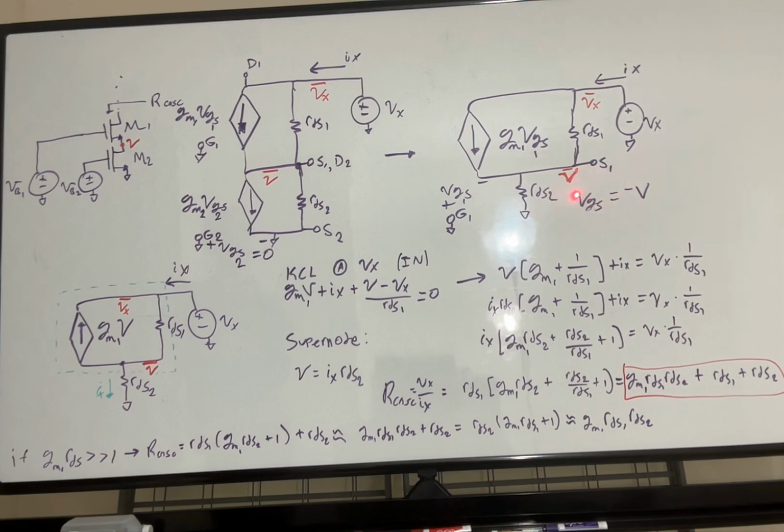So when I see that my VGS becomes negative, what I like to do is I like to redraw it but change the direction of the arrow. So now we've got a third circuit here. And all 3 of these are equivalent. We're just writing it in a way that's a little more succinct. And I've also added this green box here. This green box is the supernode box. So by supernode, we know anything that enters the box has to equal the current going out of the box.